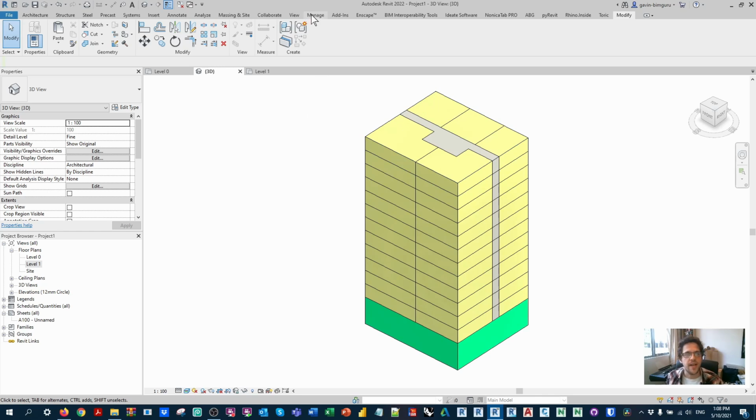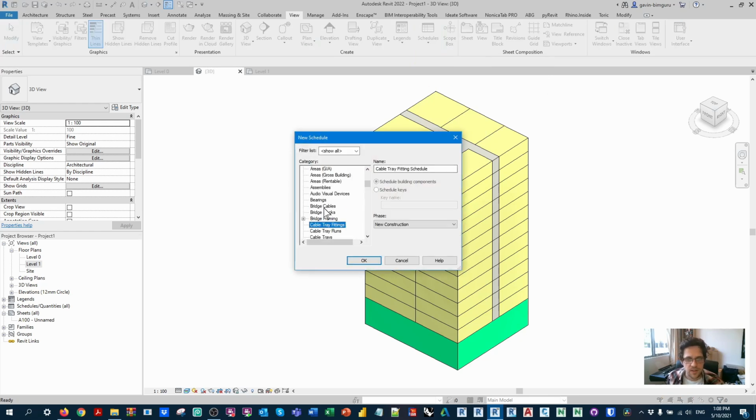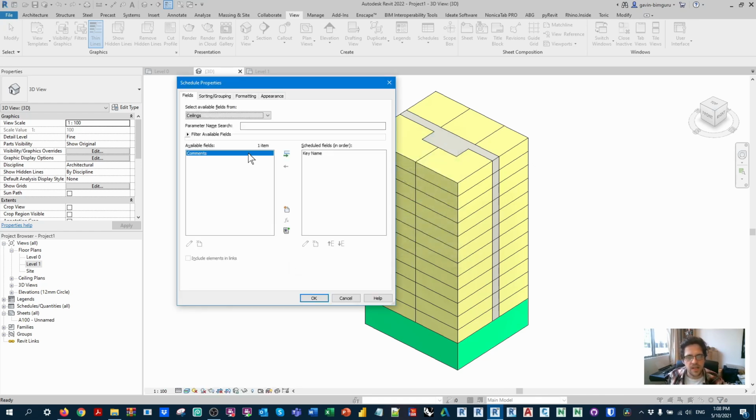Again, we can generate a new parameter for efficiency. So this time we're going to apply this parameter to ceilings. And we're going to make it a schedule key. We'll just call this efficiency. Now, I believe it's an instance-based parameter, which isn't necessarily ideal. So rather than make a key, maybe we can add a project parameter, but I'll show you both options anyway.